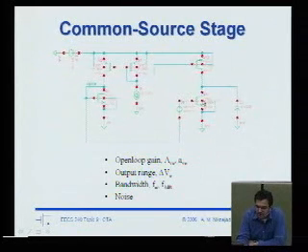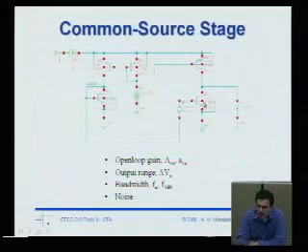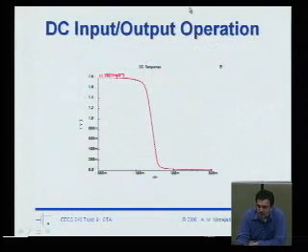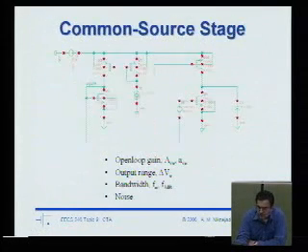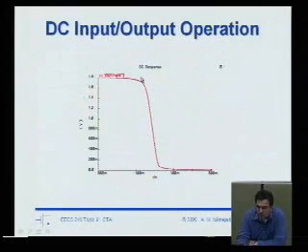Again, this is very straightforward. I'm using a PMOS load, and in homework you analyze the effect of noise from this PMOS load. We can also verify that. First of all, here's the DC input-output characteristic. I sweep the DC input and plot the output, and a digital designer would look at this and say, it's an inverter, right?